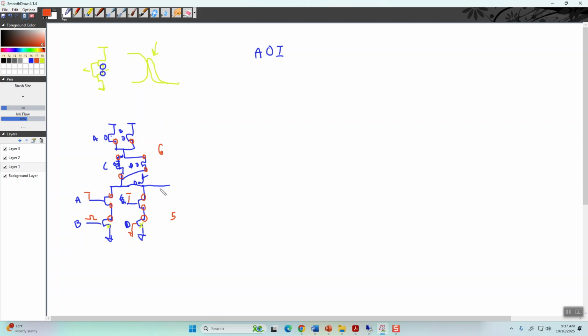You might wonder, why am I doing that, right? Well, you're doing it for the power savings, and when it comes to automatic testing, these circuits are a lot easier to test. Oh, and also, to get it to work, you add an inverter. Okay, just for those of you wondering. But this is a very compact way to do circuits, right? You can do whole adder chains like this.